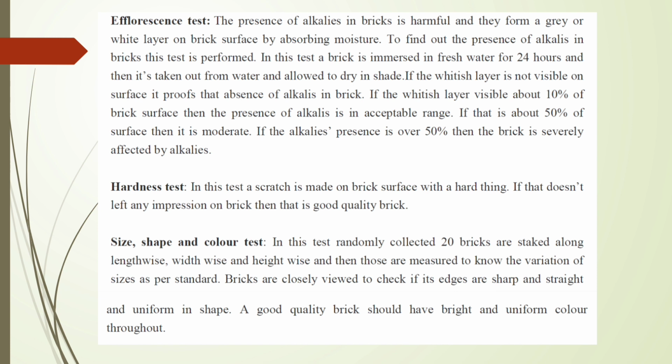In this test, randomly collected 20 bricks are stacked lengthwise, width-wise and height-wise, and then those are measured to know the variation of sizes as per standard. Bricks are closely viewed to check if its edges are sharp and straight and uniform in shape. A good quality brick should have bright and uniform color throughout.